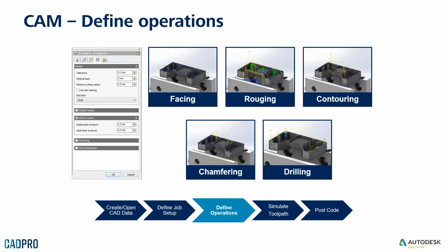From there, you define all your operations, so typically facing, then remove all the material, do some detailing, and then some finishing, drilling, tapping, and so on and so forth.